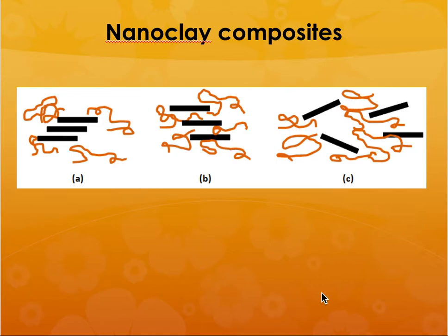portion where that extra nano-sized filler can cause some kind of agglomeration and start the crack or cause a weakening of the material at that point and start a failure at that point due to the excessive agglomeration of these nanoparticles. So that is the biggest challenge with regard to these nanoparticles. But there are several advantages due to these nanocomposites.